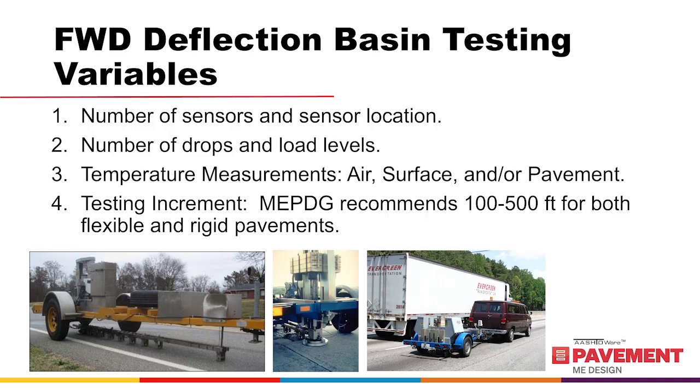Next is the load level and number of drops. First, the number of drops from the same drop height, which is 1 load level. The LTPP program recommends multiple drops from the same drop height, or at least 2, but preferably 3 at different load levels for both asphalt or flexible and rigid or PCC pavement from a repeatability standpoint.